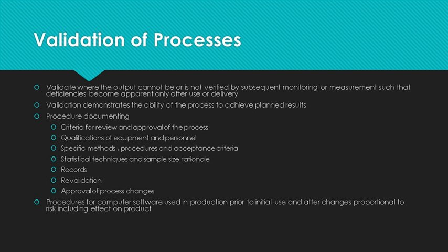Of course, this is ISO 13485, so you need a validation procedure documenting the criteria for review and approval of the process, qualification of equipment and personnel, specific methods, procedures, and acceptance criteria, statistical techniques and sample size rationale, records, revalidation, and approval of process changes.